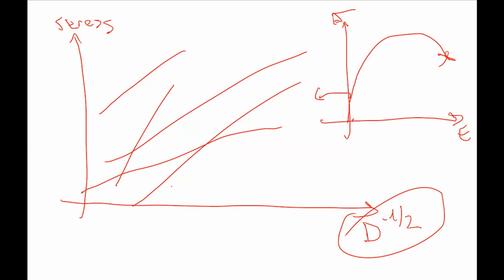Here we have less dislocation density, and once we elongate the material, we will have more dislocation densities, and the dislocation density increases as the plastic strain increases, and dislocation tangles and cells will increase like the subgrains, and we will increase the strength due to grain boundary strengthening.